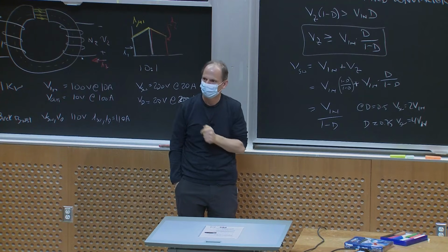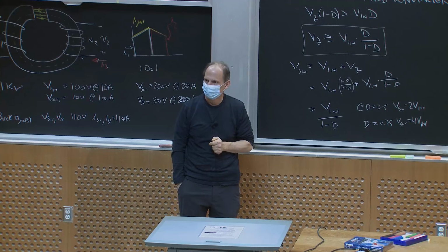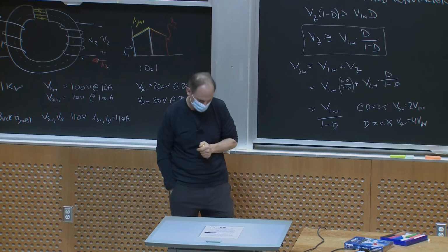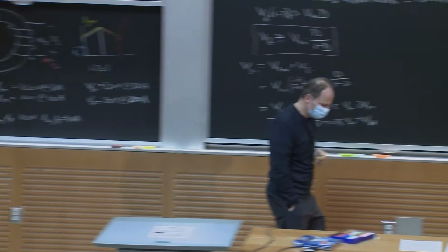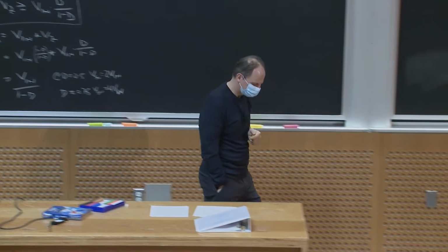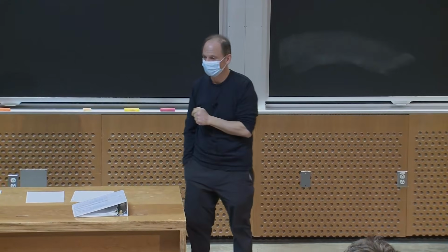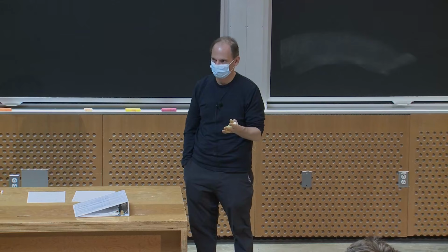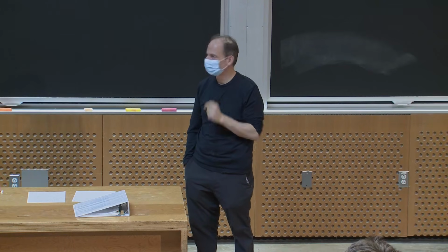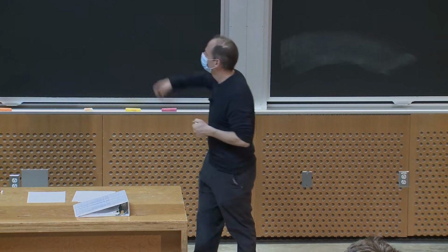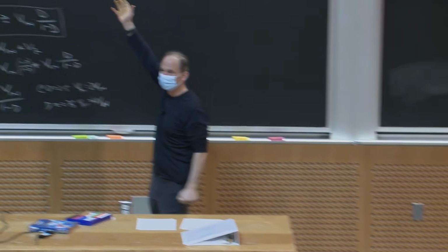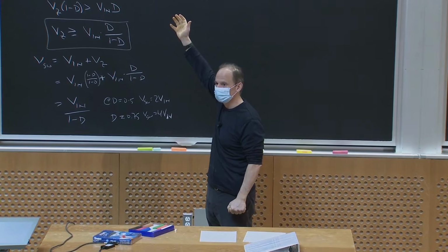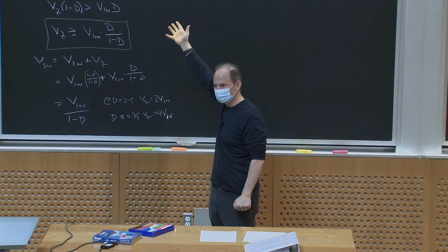Yeah, Jack? How would you use the forward converter over the flyback? Ah, that's a very good question. That comes back to how big it is, and we'll talk more about this. But remember, a buck converter is a direct converter and has very low stress on its switches and low energy storage in its components.